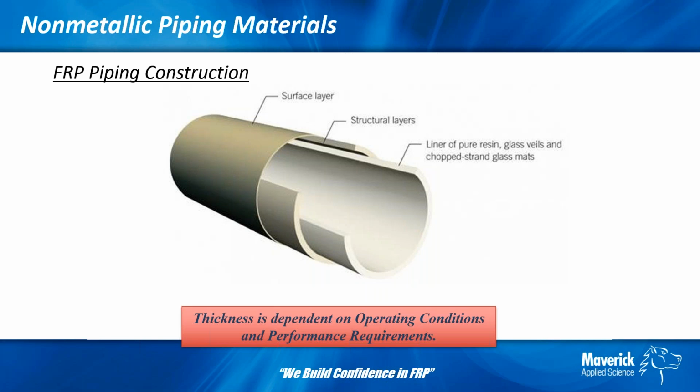So we're talking about the sun beating down on it, the rain beating down on it, and generally it's a direct wear issue that is probably the biggest concern we see with piping on the exterior layers. People ask us because we see fiber bloom occur over a number of years, and generally we say that if the pipe were steel, we might want to see it repainted every 10 years or something like that. With FRP, it's that same thought process, where every 10 or 12 years you might want to recoat the outside and put a fresh paint coat on it. But structurally, the pipe is still very sound, and there shouldn't be a concern when we see fiber bloom